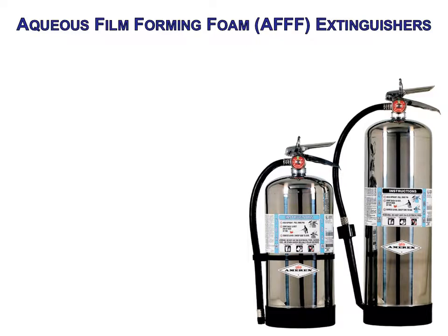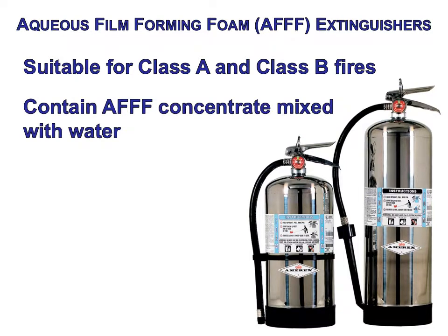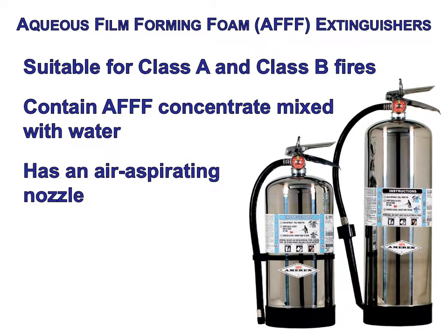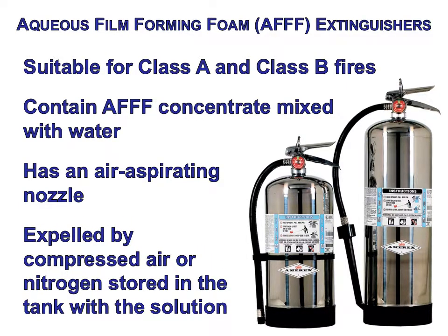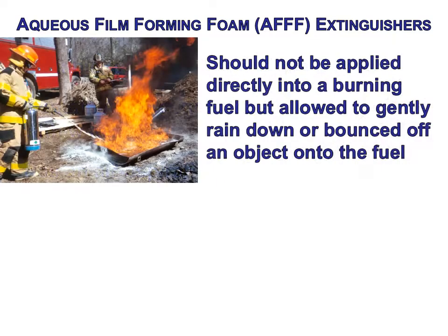Foam should not be applied directly into a burning fuel, but allowed to gently rain down or bounce off an object onto the fuel. Finished foam floats on the surface of lighter-than-water fuels. It forms a blanket which seals the vapors to extinguish the fire and prevents reignition. These are not suitable for Class C or Class D fires.